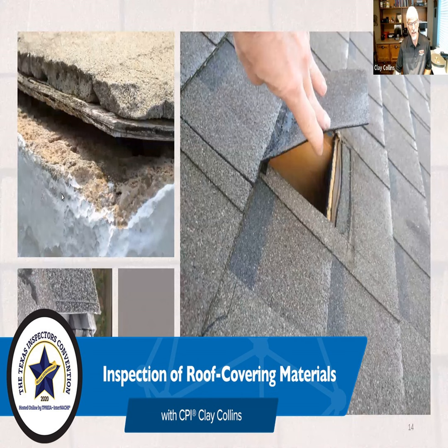If you use that silver paint to encapsulate scorched wood, typically you're going to see fire damaged wood. But if it's just a silver paint intended to be, quote unquote, a radiant barrier, in my opinion, that's a waste of paint. It doesn't satisfy anything. But the TechShield itself, I don't know of any shingle manufacturer that says that is a problem for their shingle cover performance.